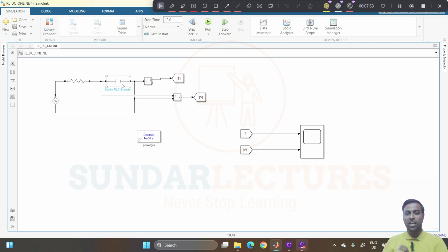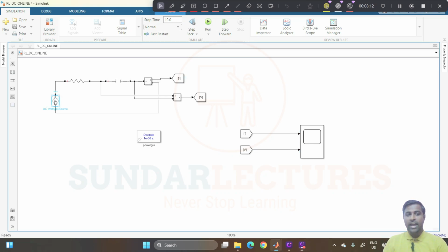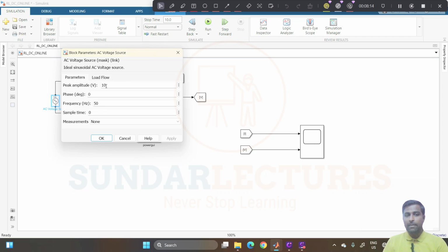We will first see the RC network, and then we will go to the RL network with the AC input, right? So you can get these values. Once again, you just connect this negative terminal to this point because we have to measure the current, right? So you connect this one to this point, and you give the AC amplitude as 10 volt and frequency as 50 hertz.